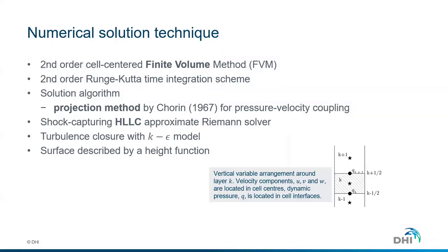It is allowing for quite robust simulations, and it is, I would say, one of the key features of this new software, allowing us to take the extra step and actually transform waves all the way through the surf zone, where we have all these processes of wave breaking, undertow profiles, longshore currents, and radiation stress gradients developing, which is actually possible to simulate using this software.